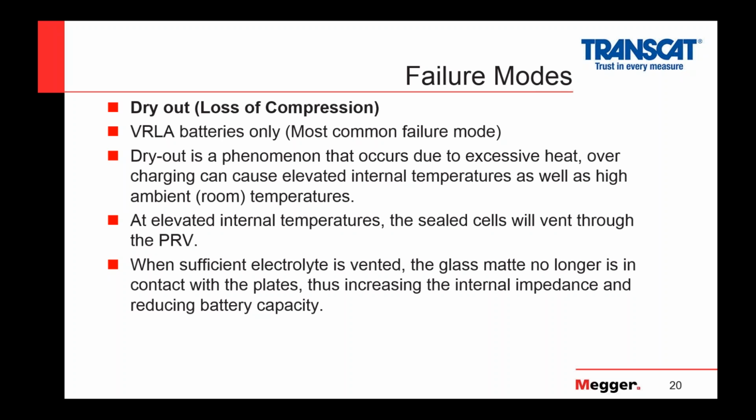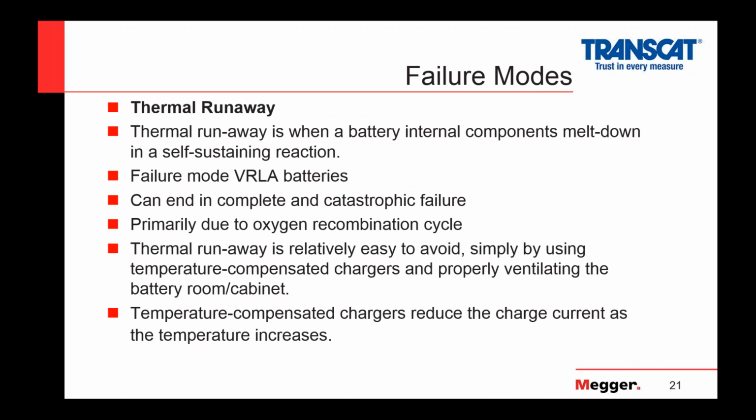Now, what can accelerate that? Heat. Just like in a VLA battery, heat is your enemy, especially even more so with VRLA. Because in a VLA battery, a vented lead acid, you can always add electrolyte. In a VRLA, you cannot. So they are temperature-sensitive batteries and should always be kept in temperature-compensated rooms. Okay, you want temperature control when you're dealing with a VRLA battery, that is. And if they get too hot, you can lose gas through them. Lose hydrogen can get vented through the valve.